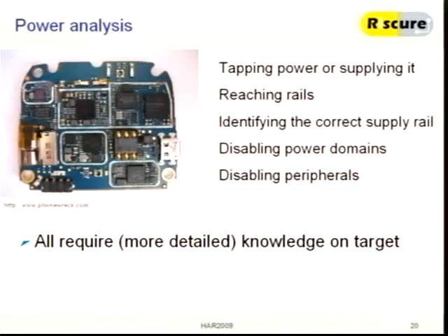No, because that's not a power measurement. What you measure then is just the input voltage. Yes, but you have current flowing from one side to another side. So we have a resistance in the PCB, and we measure the differential voltage between two capacitors.